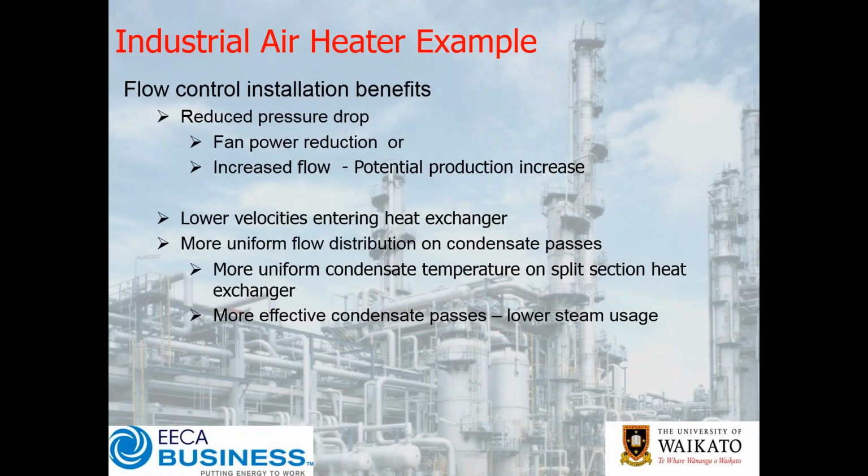In fact, we just recently were involved with a project on a heater here in New Zealand where the airflow was not very well distributed, and we've dropped the condensate temperature off the heater down by over 30 degrees, and the steam pressure required to get the production capacity of that plant has gone from 22 bar down to about 11 bar. So obviously everything's not working anywhere as hard, nothing's as stressed as much as it used to be. The condensate's nicely subcooled, so you actually use less steam, but you're using more energy out of the steam.